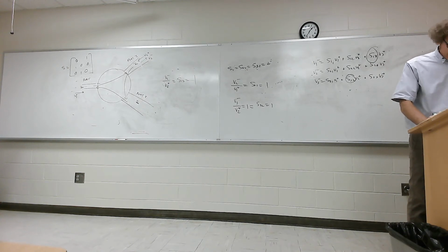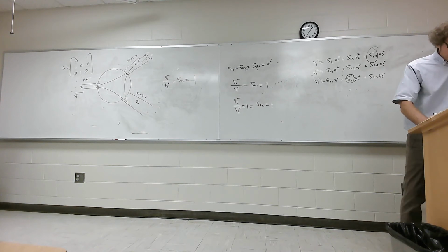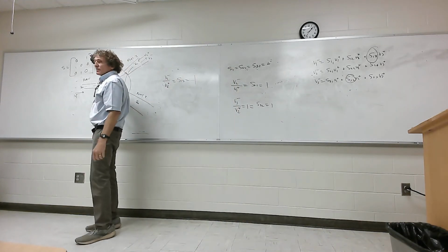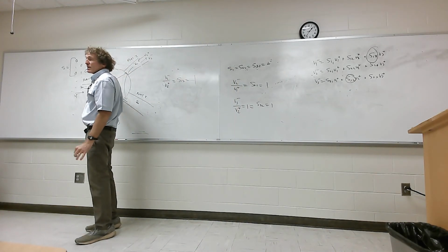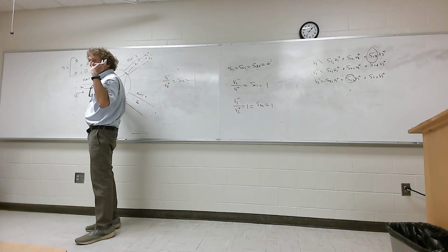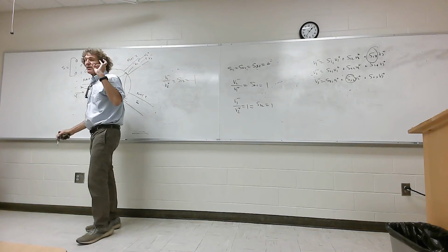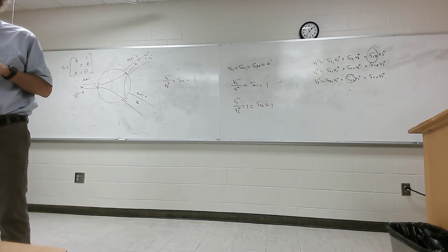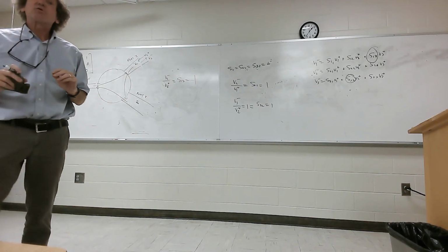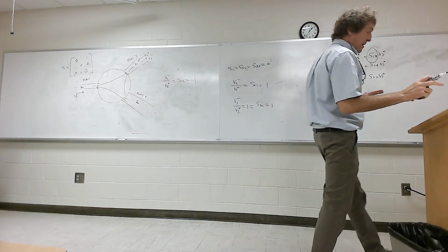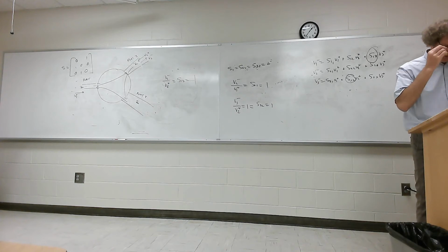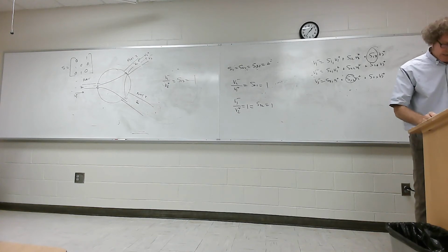Now I have to tell you one thing. It's never that good. Normally they do it in dB. They take the dB values of all these things. If you have a 1, 20 times the log of 1, what's the log of 1? 0, right? So that would be a 0. That would be a 0. That would be a 0. The other ones, you're going to get dB values that are very large, typically, to show what really is very small, to show that it's pretty well matched. Y'all follow me on that? It'll be negative cajillions kind of stuff. Actually it will be positive, but you'll see this as we do some problems.